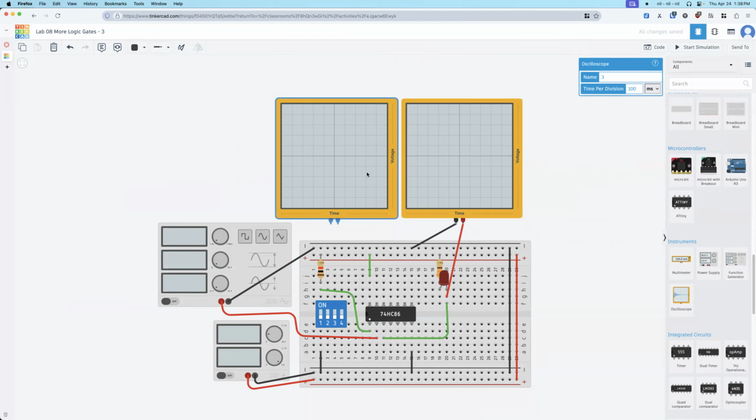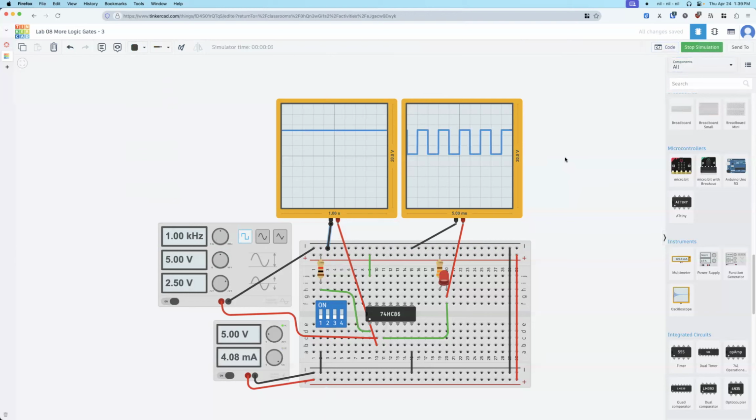But in Tinkercad, we cannot do this, so we need 2 signals, 2 oscilloscopes. Okay, so positive, so go to the input. So this is the input signal, right? Then this just goes to ground. Okay, so then we can compare these two. Okay, so this is also 5.